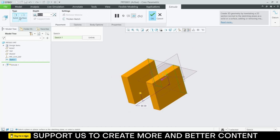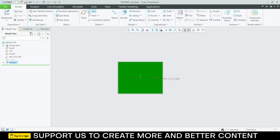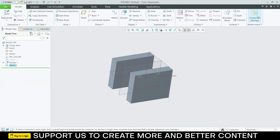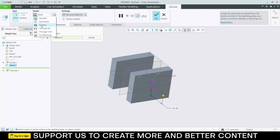So extrude up to 100, click OK, select a face, click normal to the screen, click on sketch, draw a center line at the center of it, click on the middle mouse button, draw a circle, click OK, double click, make it 50 at least, and click OK, click on extrude, remove material through all, reverse direction, click OK,